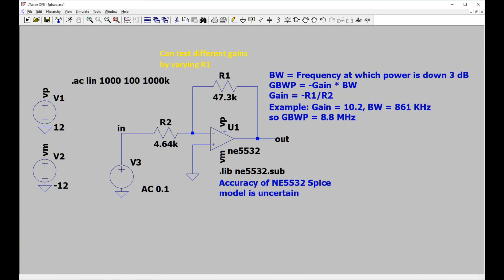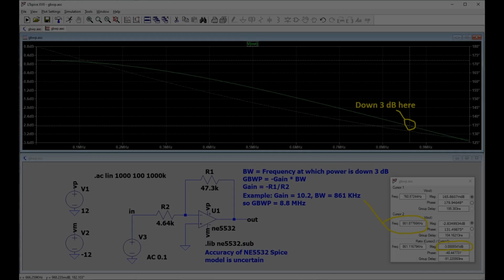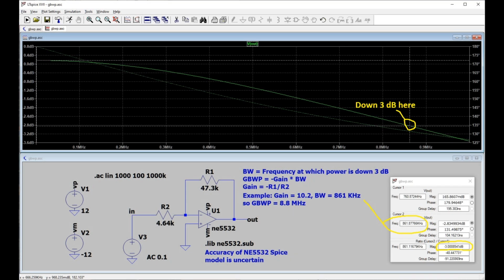The slew rate that a test imposes is proportional to the amplitude of the input signal, so the easiest way to avoid slew rate problems is to use a lower amplitude on the input signal. We can do this in an LTspice simulation using an AC analysis. That produces a Bode plot just like we can with the network analyzer on the M2K.